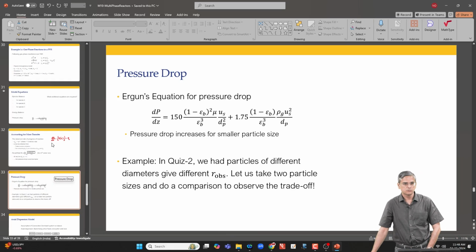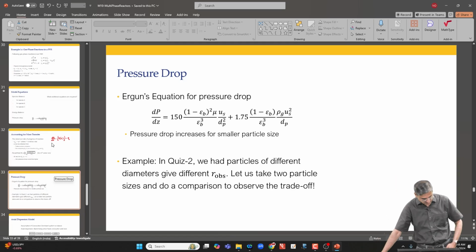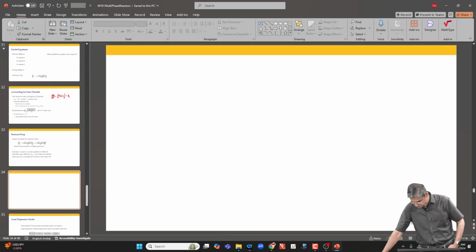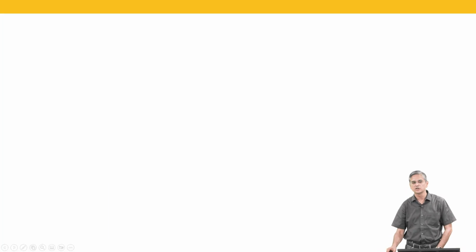Okay. Tomorrow we will take up a 1D heterogeneous model example. Just the way with internal diffusion, we combined two things: we combined the concept of eta and the concept of PFR. In the same way, in the 1D heterogeneous model, it's external diffusion and reactor.